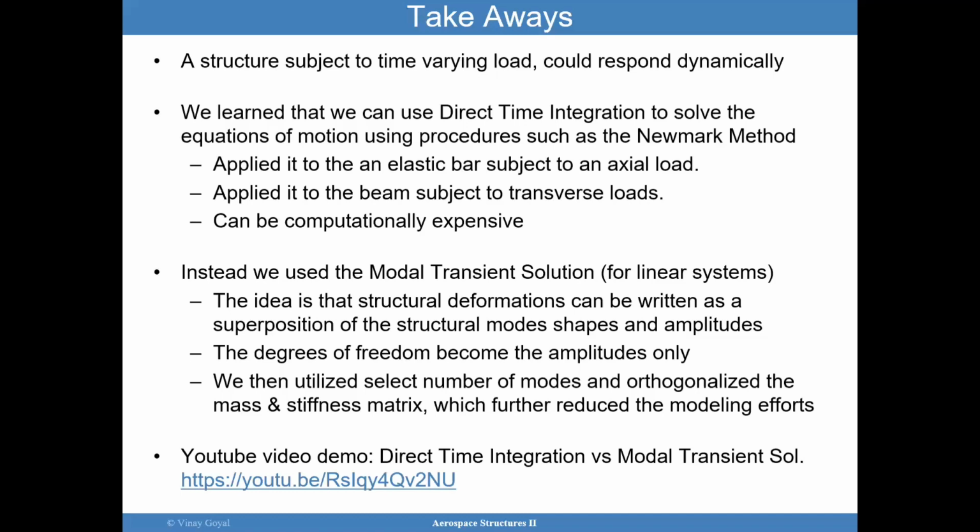The YouTube video in this link, and go ahead and type it, compares the direct time integration versus modal transient solution, exactly demonstrating that these two processes, these two modeling techniques, result in very similar answers. We also demonstrate that using a select number of modes, you also can get a very similar answer to using all the modes.